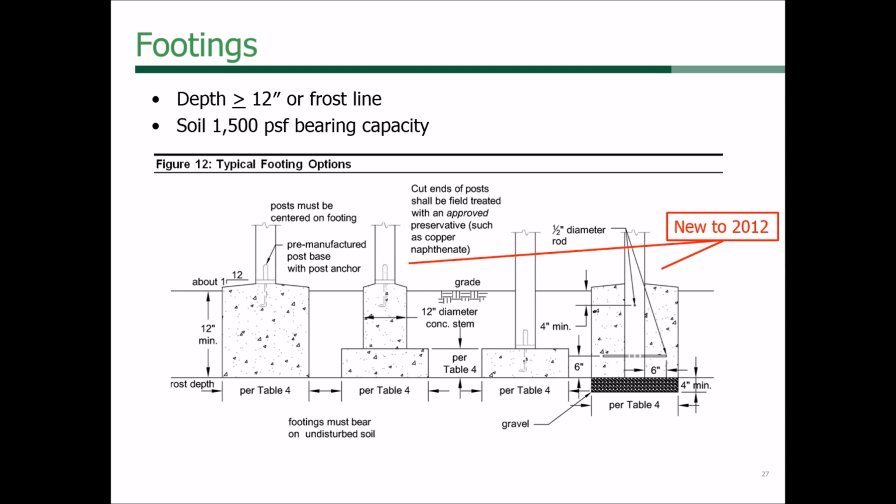We require connections on all of our posts so that it can have as much lateral strength as it can, because people run into it with mowers or whatever it is. So you want to make sure your post isn't sliding off. But the far right one in particular will add stiffness to your deck. We recommend gravel at the bottom instead of a poured concrete slab or something like that, so that when you pour the sides, you don't make a water trap. There's kind of a bucket or a well for the water just to sit and eat at the post.